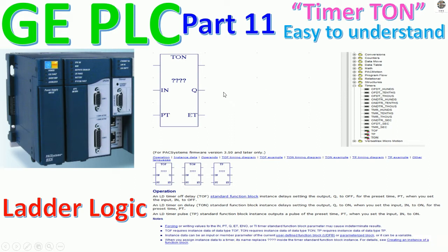Here is the block of timer on for ladder logic, and here is the tool chest where we can drag and drop the timer on from the tool chest to the project, and then we can test it also. And this is the principle of working and operation of timer on, timer off, and timer pause.